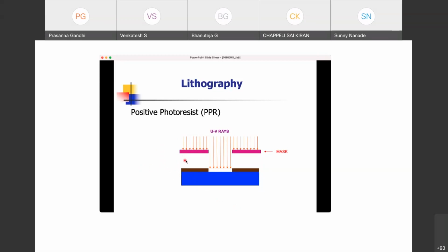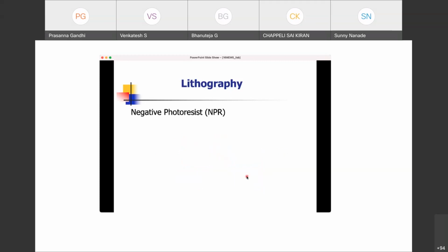That's why you need the lithography step to mask the area where you don't want the deposit to happen, or you don't want that area to get etched. That area you prevent, or mask in some way, so that whenever I take it for further processing, this area under this brown window will not get affected at all, but here some deposits will happen and things like that. So this is the basic philosophy of processing and thinking in the MEMS domain.